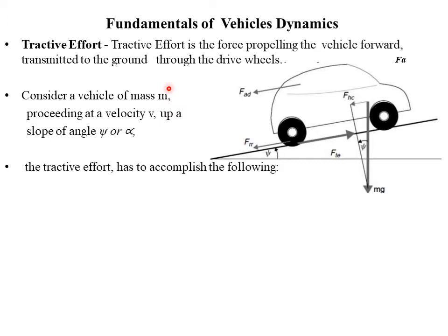And only if the vehicle has sufficient force to overcome those resistive forces, and also has the force to accelerate, then only can the vehicle move in the forward direction. So the sum of all these forces that a vehicle should possess to overcome the resistive force and to accelerate in the forward direction is called the tractive effort or tractive force.